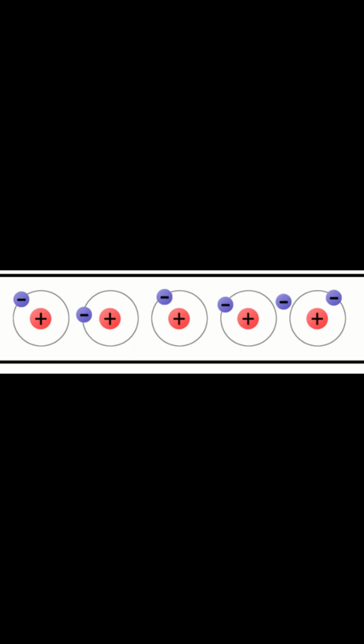The hot conductor supplies power to the load. The grounded conductor or neutral conductor provides the return path that completes the circuit back to the power source. The grounding conductor is generally connected to the case of the appliance to provide a low resistance path to ground.